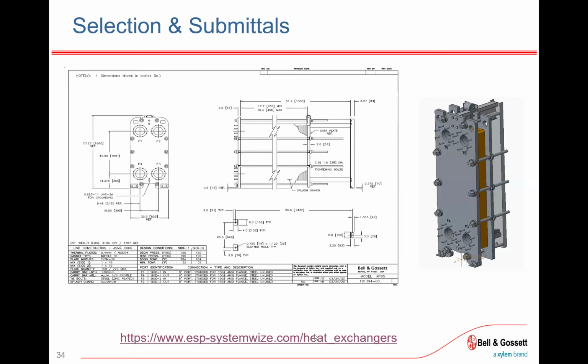air is a great insulator. So you think about that plate's ability to transfer heat as it is, versus having that air gap in between. It's going to require much more surface area and more turbulence to be able to achieve that same heat transfer if we've got an insulator in between every one, right? So that always has to be kept in mind.